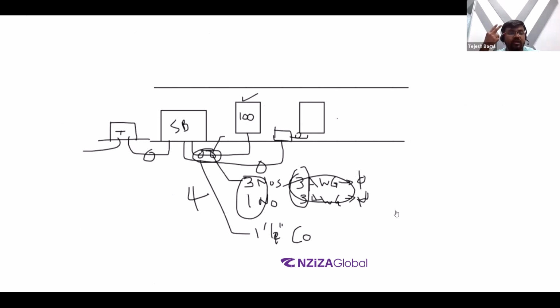But phase and neutral is what we are talking about over here. So basically trying to have a standardized American wire gauge size for the given 16 amps. So what note you can put on your drawings is that the given conductor size needs to be a minimum, let's say, 12 American wire gauge, in case it is not noted on the given particular plan or riser diagram.